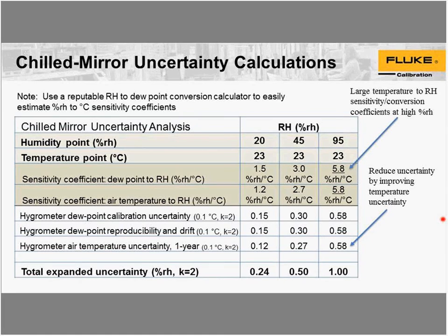One manufacturer recommends very limited flow, almost static air on the remote head, but the other manufacturer recommends turbulence, and I've seen in measurement that the two mirrors respond differently. It's really important to talk to the manufacturer and find out what they recommend. They talk about flow rate and whatnot in their manuals, but sometimes some of those details aren't in the manual.